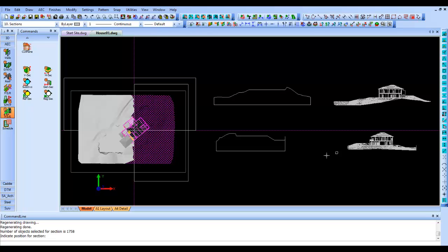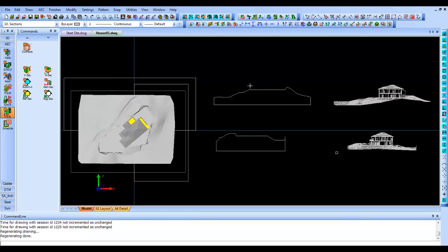The last step that I want to show you is to place our picture, to drape it on top of our DTM. As our tin model consists of a lot of triangles, I need to convert this to one polyface mesh. Let's select redraw and continue. After creating the polyface mesh, I will disable the triangles and then drape the picture.